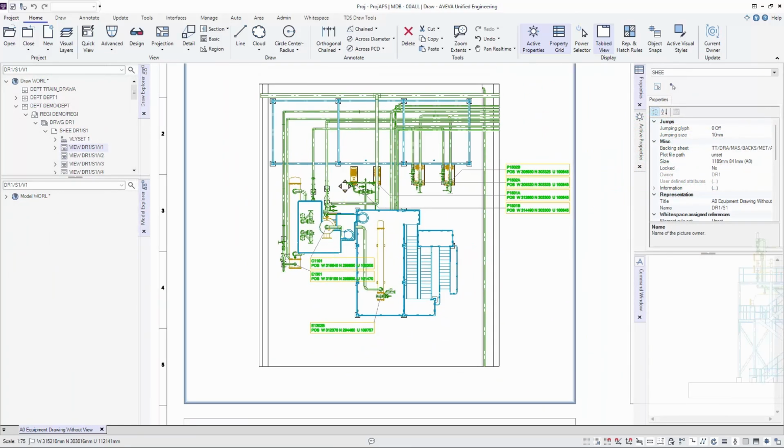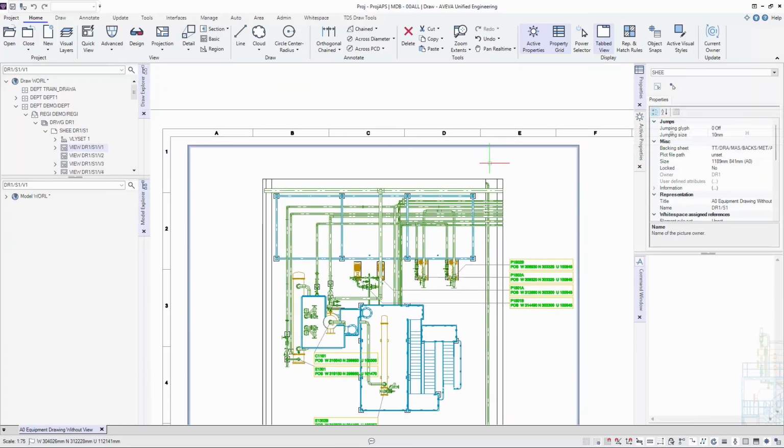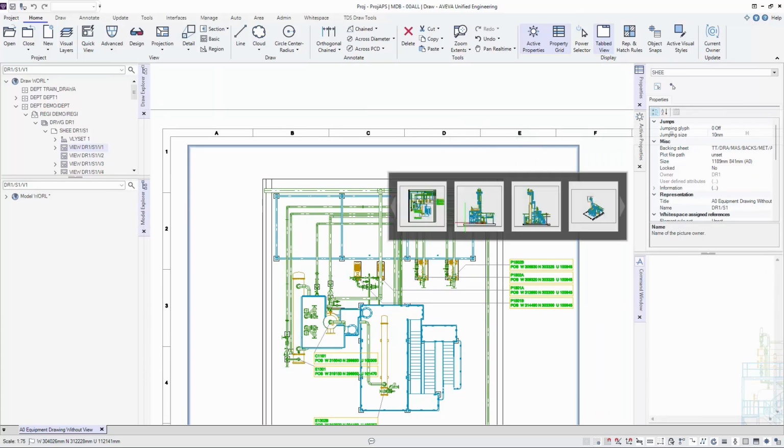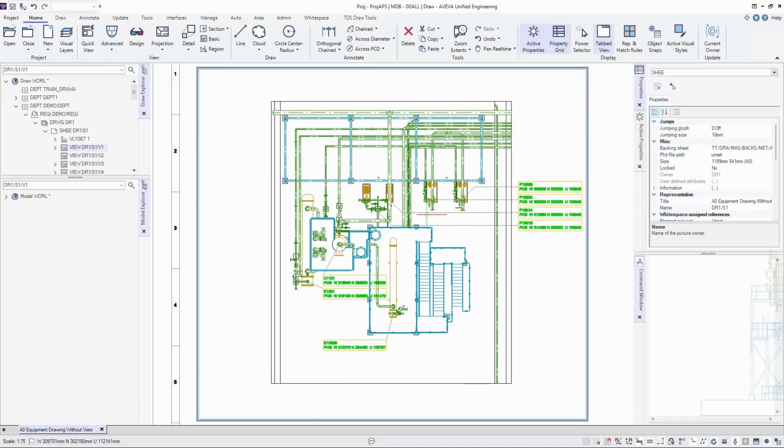We'll start by introducing the different types of linear dimensions available in E3D Design. There are 3 main types. Chain dimensions, used to place a series of measurements end-to-end along the same reference line. Combined dimensions, where the dimension is shared, allowing values to be shown both to the left and right from a common reference. Baseline dimensions, where all the dimensions start from a single baseline, making it easy to compare multiple distances from one fixed point. Let's begin by creating a chain dimension.